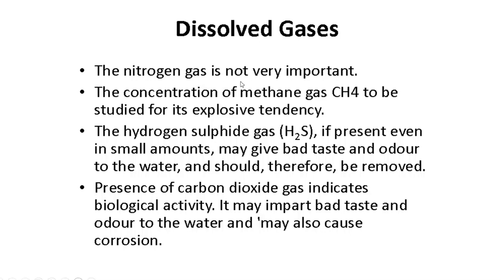Nitrogen gas is not very important. The concentration of methane gas, CH4, is to be studied for its explosive tendency. On the other hand, hydrogen sulfide gas, H2S, if present even in a small amount, may give bad taste and odor to the water and should therefore be removed. Presence of carbon dioxide gas indicates biological activity. It may impart bad taste and odor to the water and may also cause corrosion.